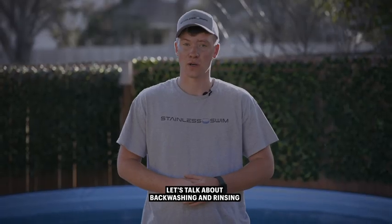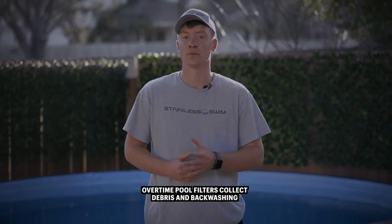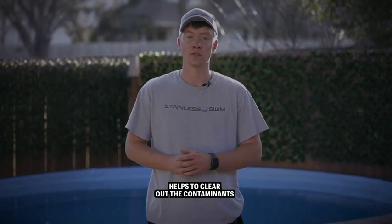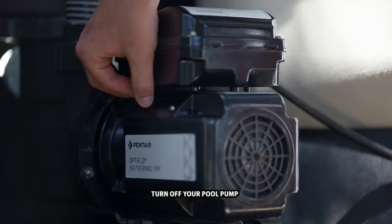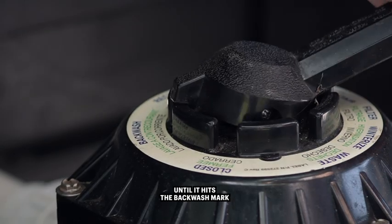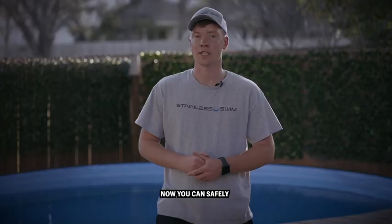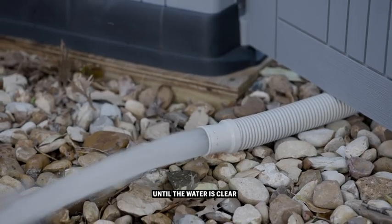Let's talk about backwashing and rinsing pool filters. Over time, pool filters collect debris, and backwashing helps to clear out the contaminants. To allow for backwashing, turn off your pool pump, apply pressure to the multi-port valve, and turn it clockwise until it hits the backwash mark. Now you can safely turn the pump on again and allow the cycle to run until the water is clear.